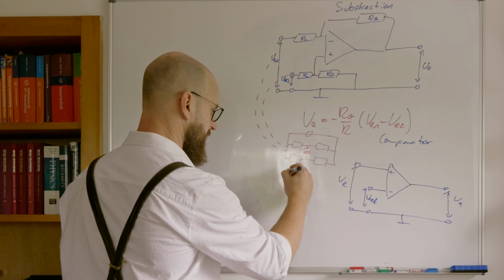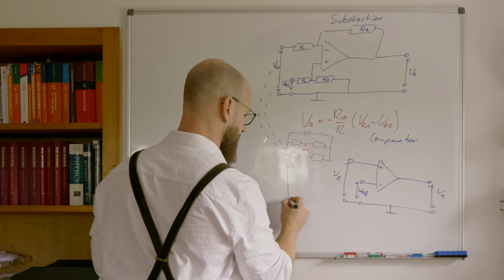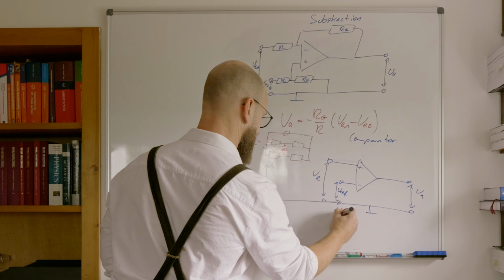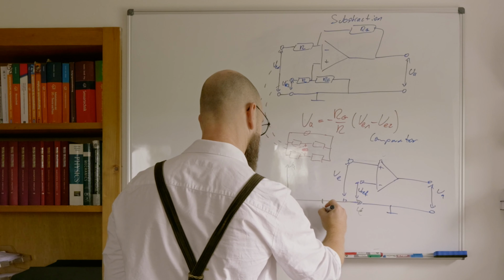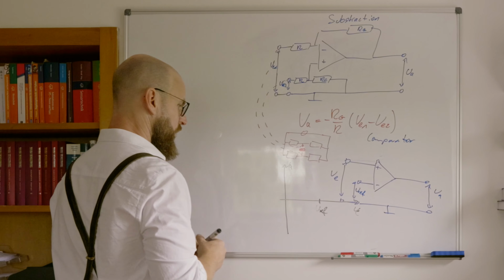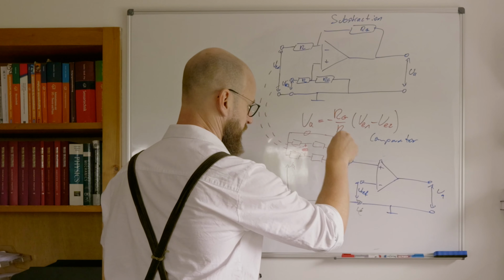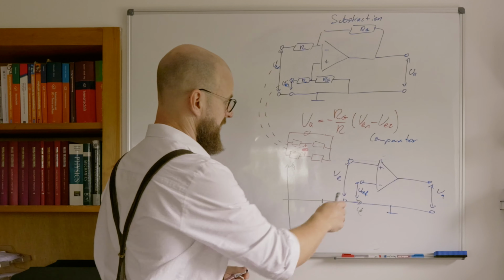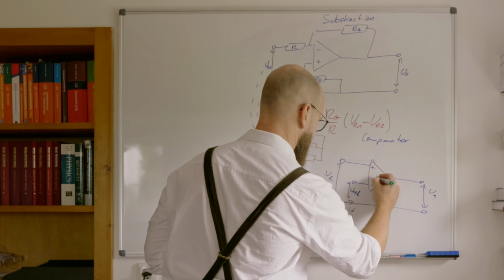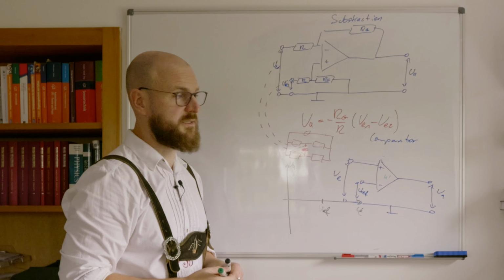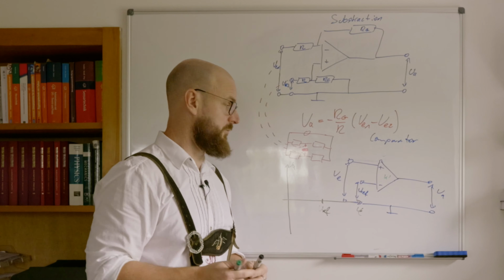Think about that output voltage being here and that input voltage being on that axis, and now denote the reference voltage over here at that place. What will happen is the following. Whenever we are smaller than the reference voltage, we have a negative input over here, and that will be amplified as hell by that factor over here, 10 to the 6 or nearly infinity, or even infinity for our ideal operational amplifier.